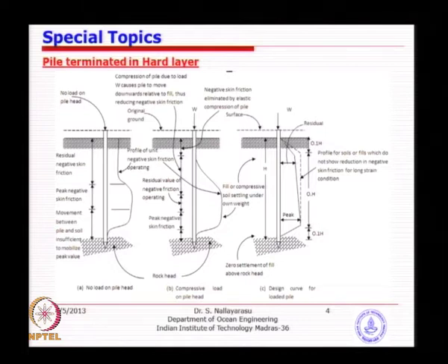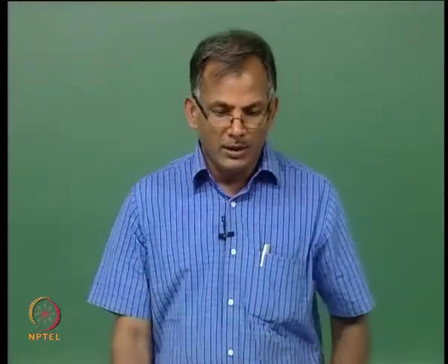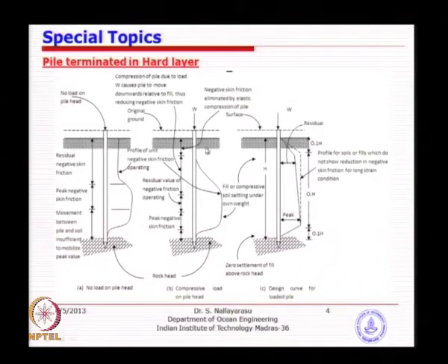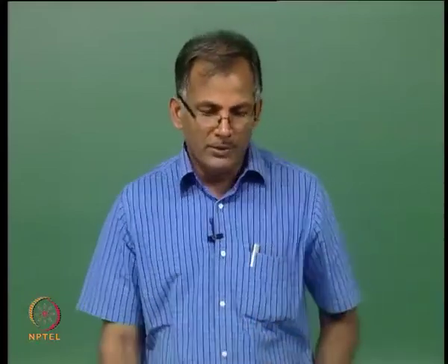of down drag. So, you can see here the top 10% is not quite a small value, increasing to the maximum value, and then this is 0.8, the 0.8 is missing here. So, 80% of the pile will be having uniform down drag, then the last 10%. So, it is a kind of simplified assumption in order to do a design activity rather than taking a highly non-linear profile, something which was measured in some of the sites. So, install a pile, do instrumentation to measure the friction, and then you look at a profile something like this.